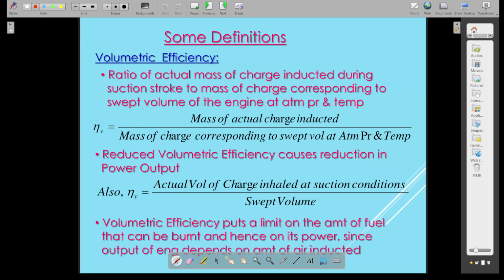Then is the volumetric efficiency. So volumetric efficiency is actually volume of air actually taken in divided by piston displacement volume. So generally I say number of times this is piston displacement volume. जैसे पहले भी मैंने आपको बताया था piston displacement volume. So I generally write eta V. Eta V is volume of air which is actually taken in by piston displacement volume.